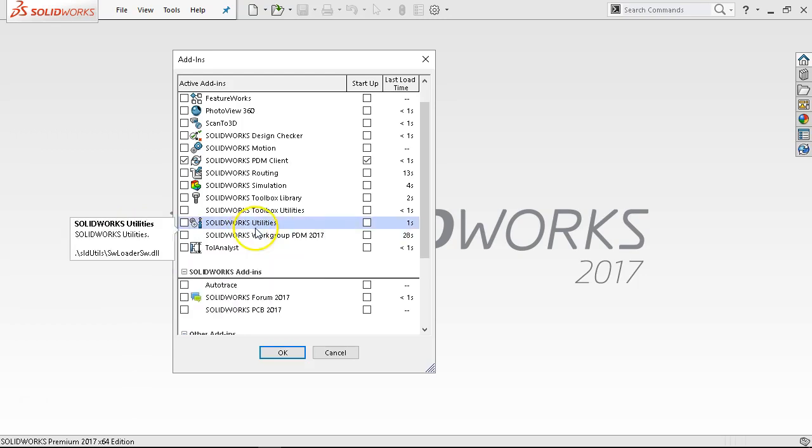The SolidWorks Utilities as a whole is usually comparing documents. All right, I have two drawings, two revisions of a drawing. I can't really tell what the differences are. It will show me the differences between two parts. It'll show me the differences between assemblies. I can set up the parameters to say this drawing has these dimensions. This is what has changed between those two.